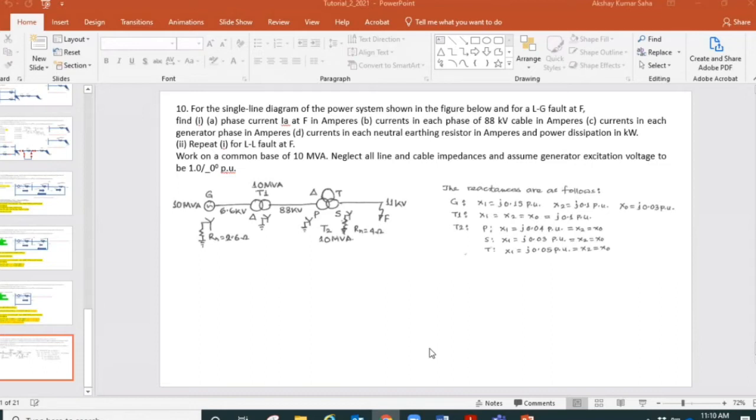So 99% is coming from the fundamental, 0.2% from the second harmonic, the third one will be less than that, so 0.15 from the third harmonic, 0.10 less for 200 Hz, the fourth harmonic, and the fifth harmonic will be less.